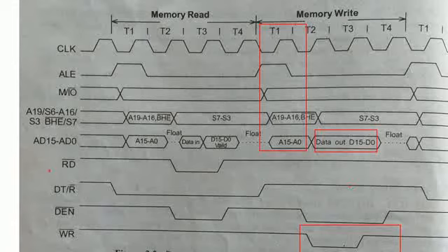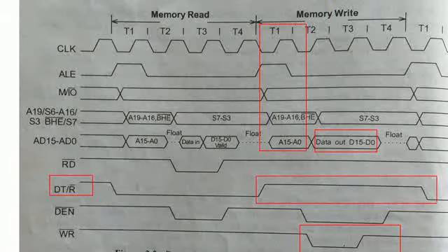Okay, so another signal status is DT/R bar. Here we are performing the write operation, means information is transferred from the microprocessor to the memory. So the signal status is active high, means we are performing the transmitting operation. The microprocessor is indicating that it is transmitting. DT/R bar is used for indicating the direction of the data flow. Simple case. It is showing the data is coming out from the microprocessor to the peripheral device, which may be the memory device. Okay.